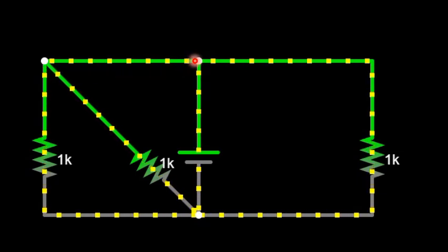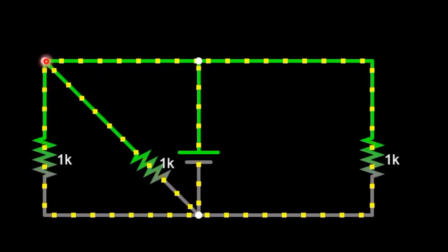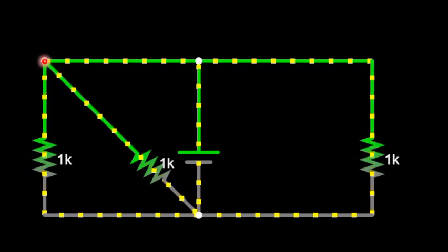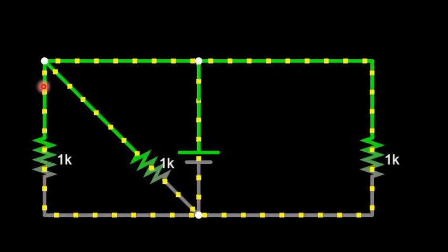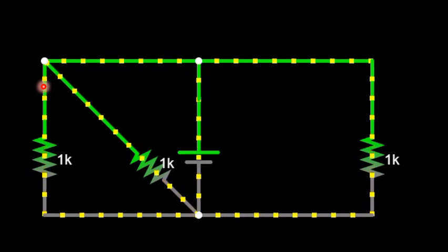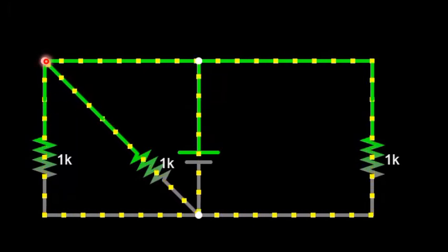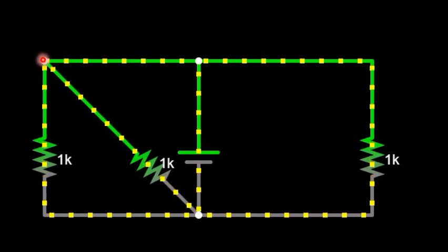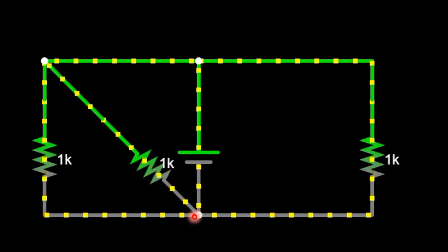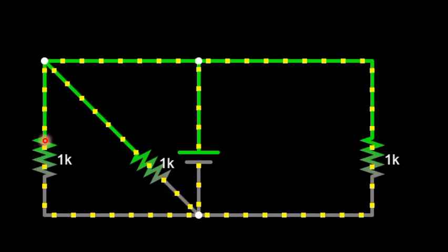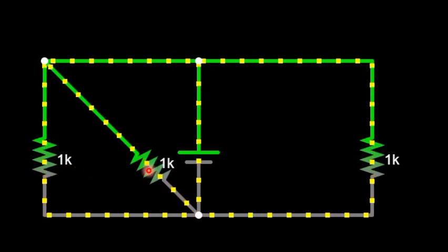Moving forward, at this side too, you see that the current gets here, then splits. So let us use the trick I showed you to see whether we can identify the parallel networks. When we circle from this node to this resistor and all the way back here, we didn't meet any third element, meaning this and this are in parallel.